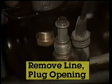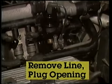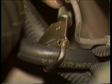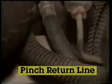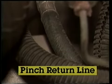Make sure the pump and return line are both okay by blocking flow through the return line. Remove the line and plug it if needed. An easier way to block flow in the fuel return is to install a clamp around any rubber hose. An even easier way is to squeeze any rubber hose in the return line with a pair of pliers.